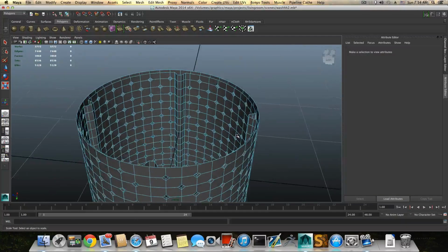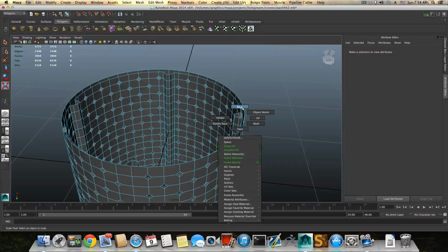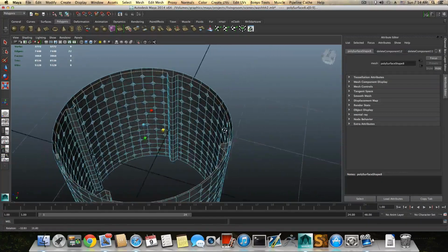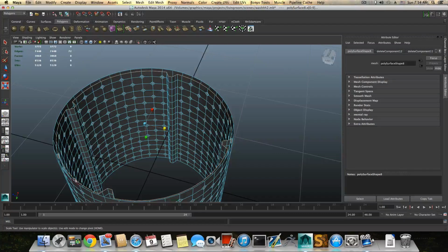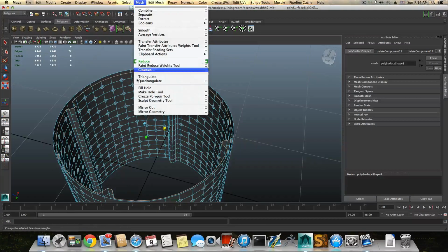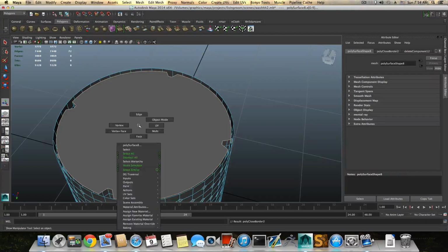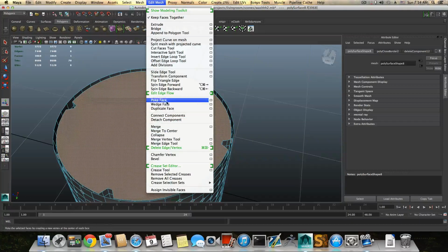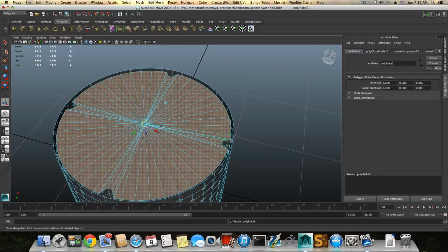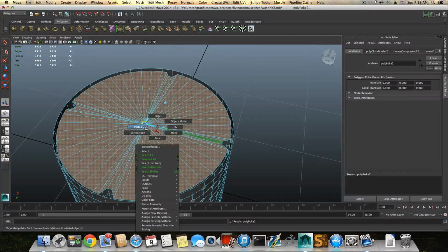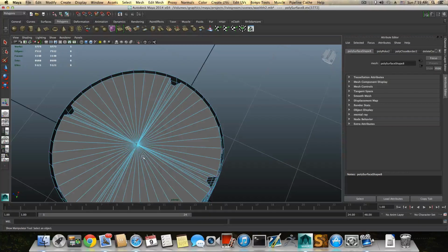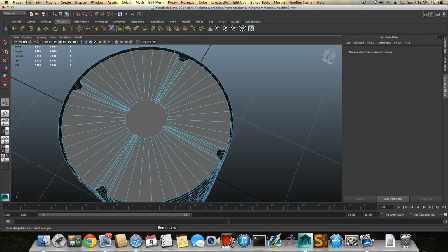Okay, now right click edge, double click on this inner edge. Okay, so it will look like this. It will select everything and go over mesh, fill hole, right click, choose face, grab this face, add it to mesh and poke this face. Okay, then right click vertex, choose this middle vertex here, hold on the shift, right click, chamfer vertex, so you will get something like that.